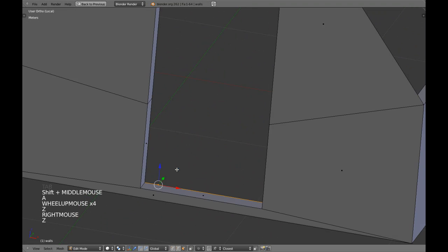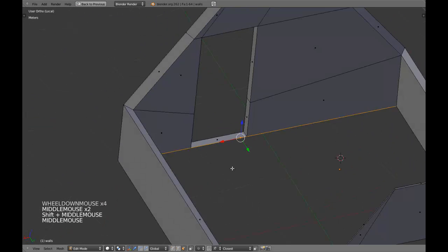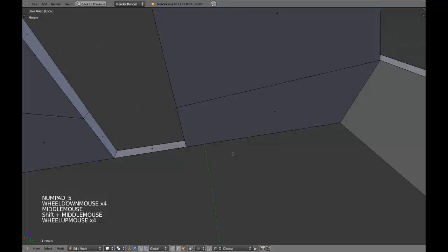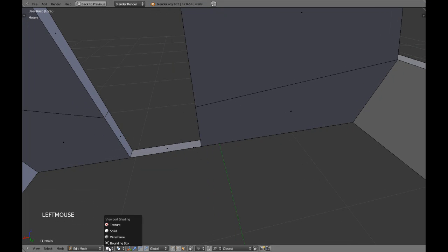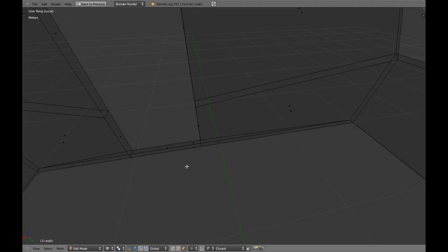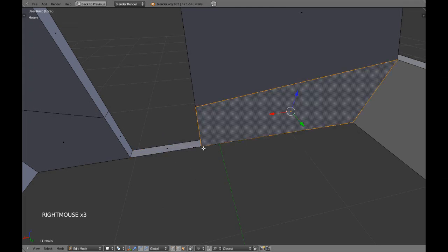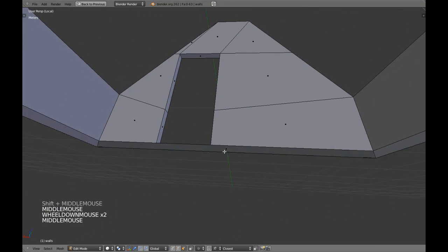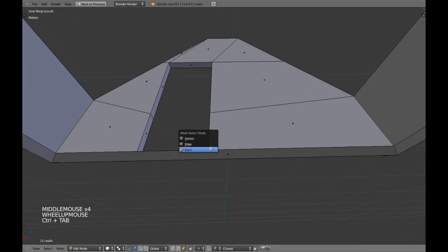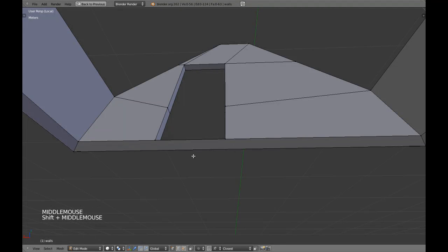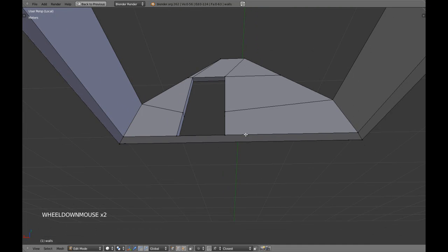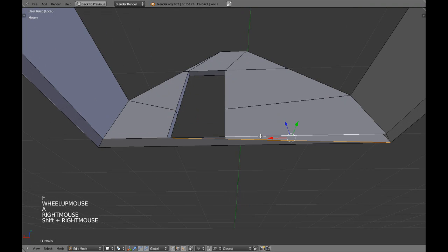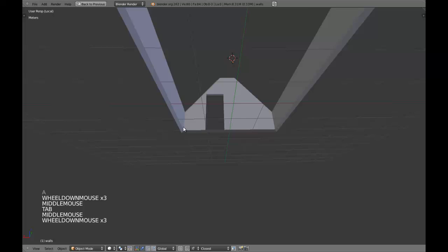that's working for us. Okay, I just select the face. If you don't change the view from solid to wireframe, you're maybe not going to be able to select it. So with C, you can do it very easily. We have this face in here which is not working at all because it has more than 4 vertices. So we're going to delete it and just select this section here and fill these 2, fill, and it's working.